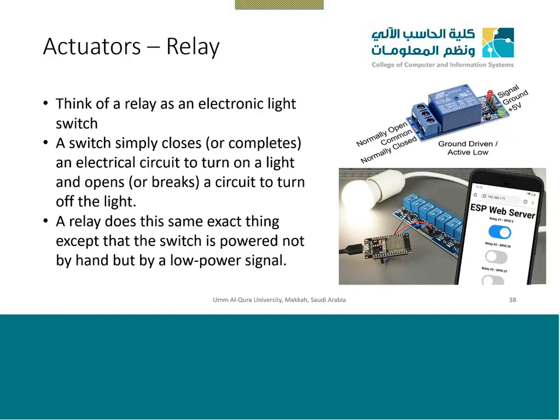These smart devices are already quite common, they are already around you, but the basic concept is how to deal with this thing with the internet, so another device can turn it on or off. So we have a relay which is connected to a web server, and we are using a Wi-Fi module. From the web server, the mobile phone will ask my gateway or my router to send the data to this Wi-Fi device. It will ask the relay. You can see at the bottom we have 6 or 7 relays.